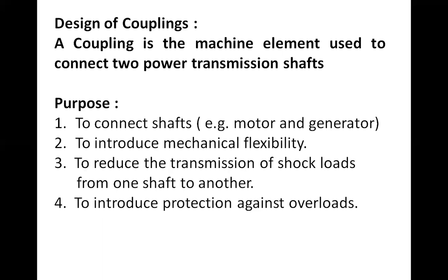A coupling is also used to permit some kind of misalignment, so it introduces mechanical flexibility. Again, to reduce the transmission of shock loads from one shaft to another, couplings are used. To introduce protection against overload, that means it is also a safety device. So this is the purpose of a simple coupling.